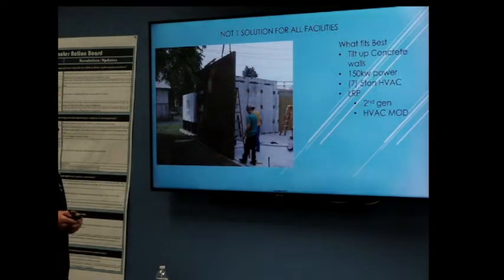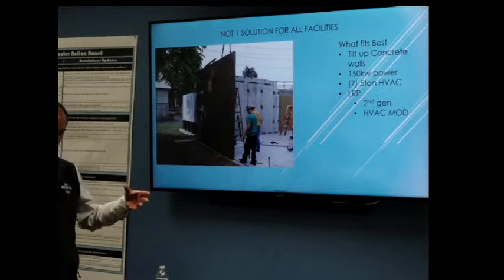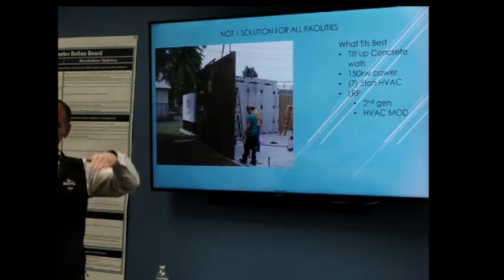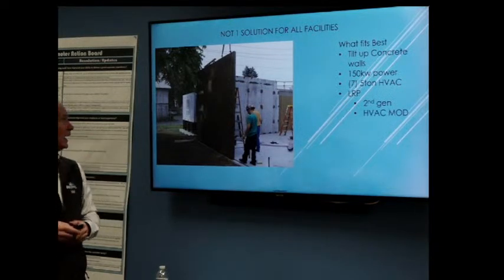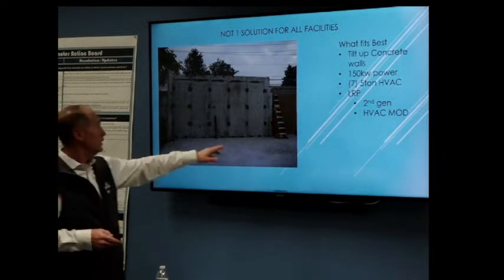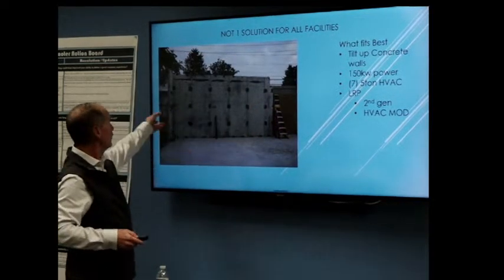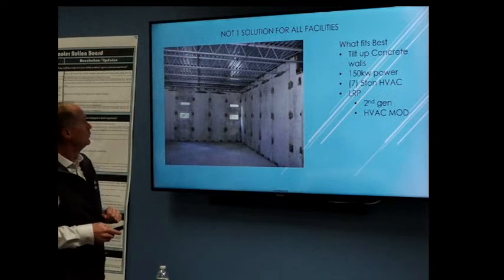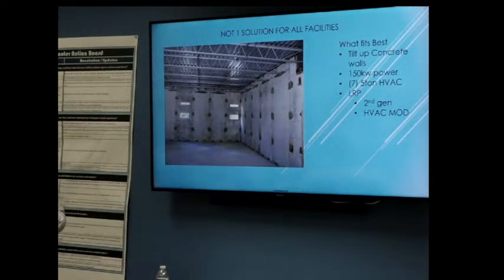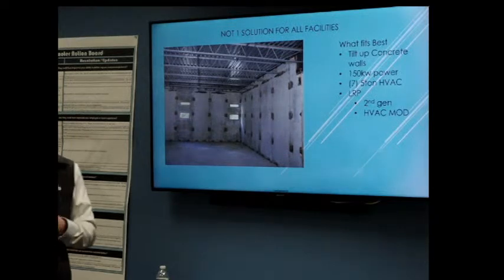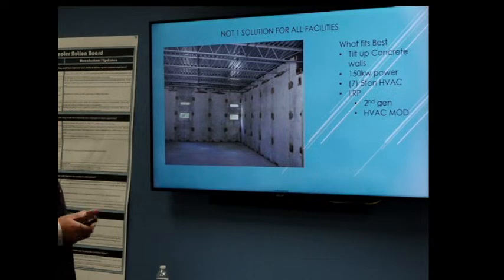There are some more techniques that we utilize. This is called a tilt-up concrete wall construction. Instead of actually being able to cart in a whole building or cart in and do CMU masonry, what we were able to do is pre-engineer concrete panels that get welded together. And by doing this, you're actually able to lower your construction costs. You don't need a crane, you don't need heavy architecture, you don't need heavy materials, you don't need a pumping truck, you don't even need a lot of CMU.